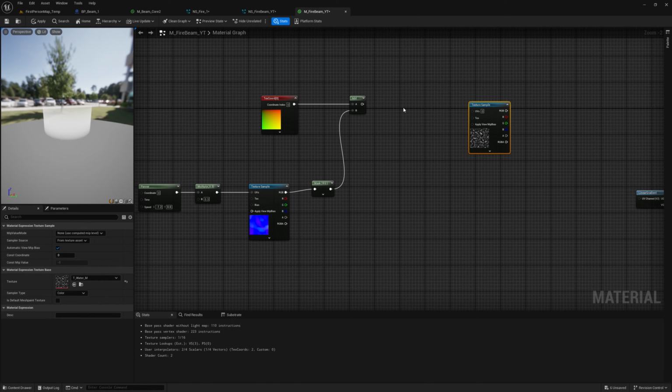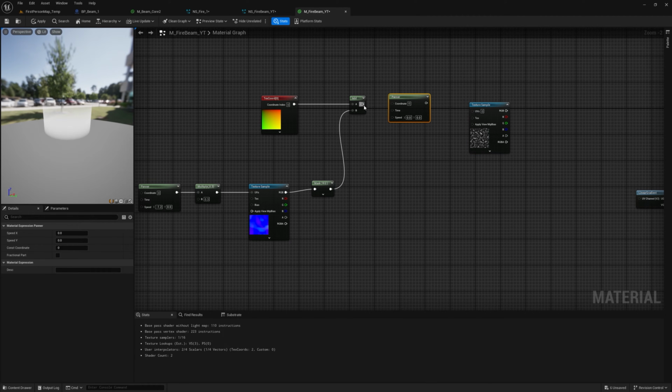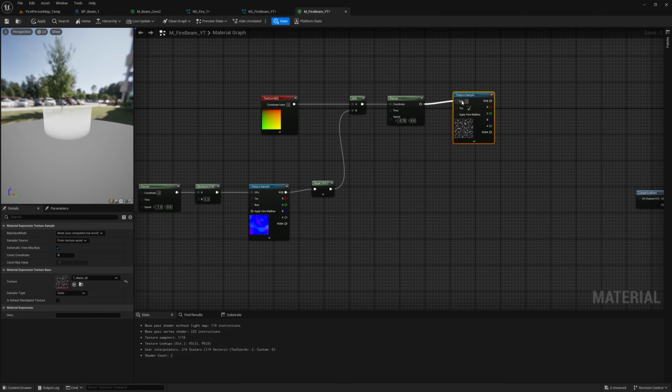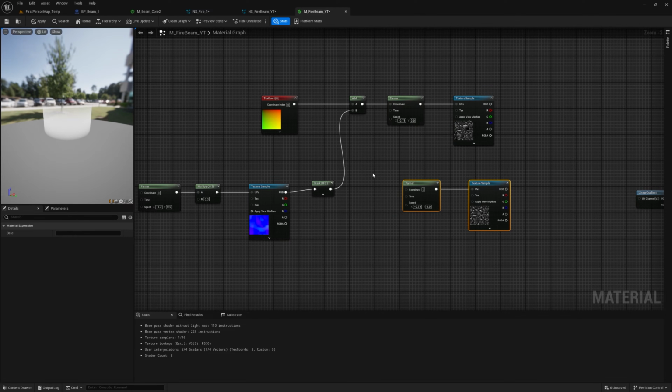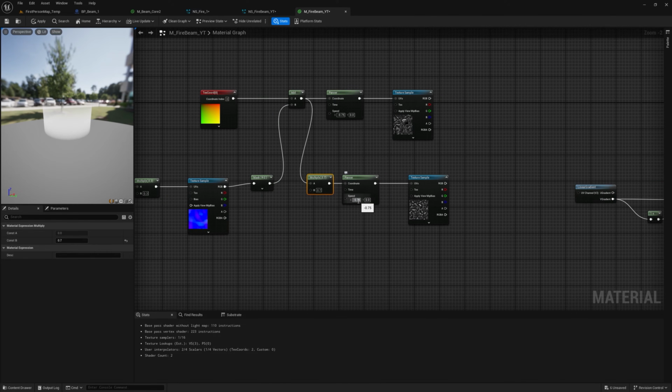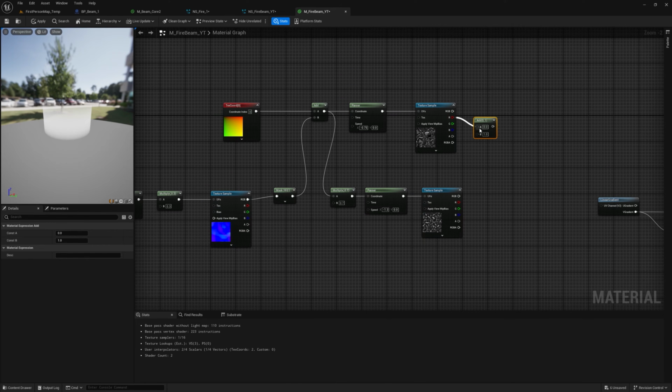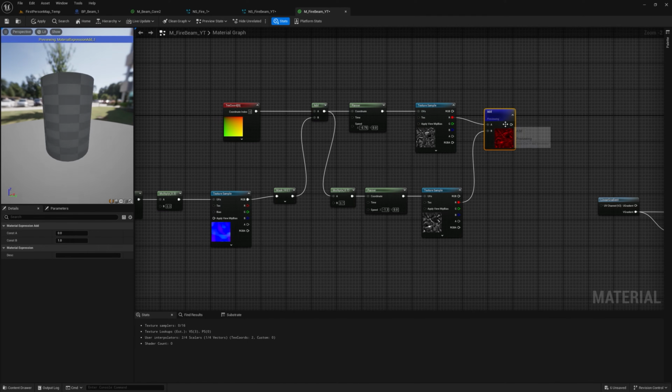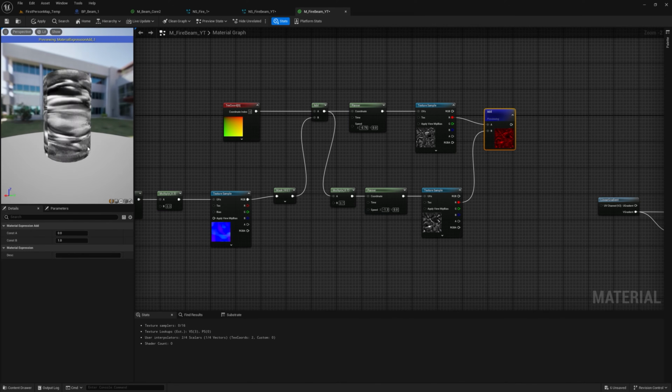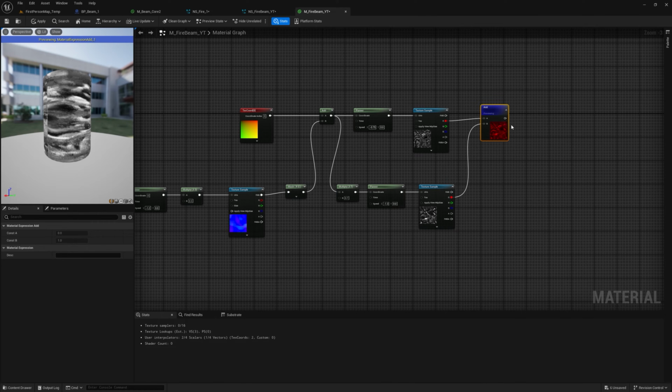Now we can get another panel. So press and hold P and click. And now connect it here. And now give it a value of -0.75 and connect it here. Now duplicate this and get a multiply node and connect it here and connect this to the panel and change this value to like 0.7 and now change this value to like 0.1, -1.3. Now add both red channels together. So now if I preview this, we get an effect like this. So I will just stop previewing.